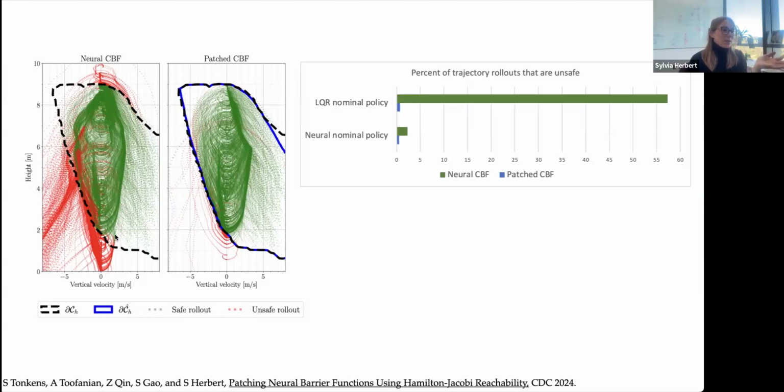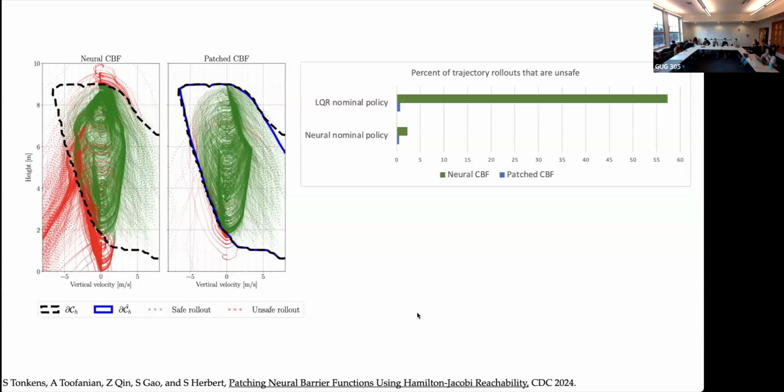So often the learning-based approaches really focus there, and they focus less on making sure that you have nice convergence when you're outside of the safe set. They really want to make sure that the QP is feasible along the boundary. They care a little bit less about whether the QP is feasible inside or outside of the boundary. If that makes sense. So often these CBF approximations are not valid on the boundary, but second, they're certainly not valid outside of the boundary on either end. Gotcha. Cool, thanks. Are there any other questions? Okay, cool. Yeah, go on.